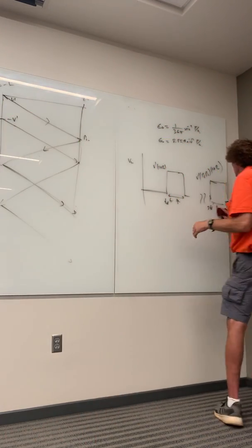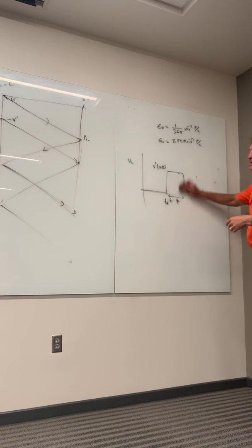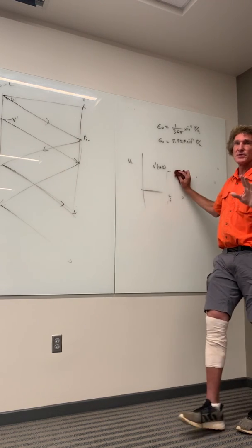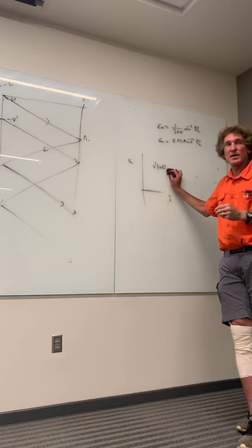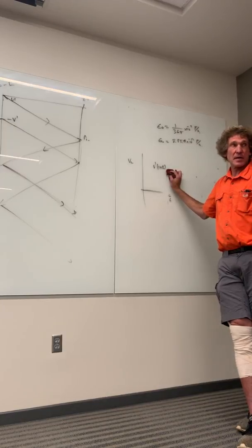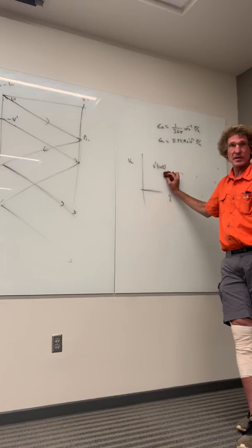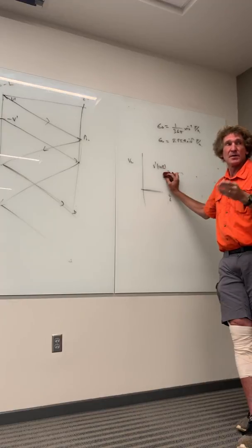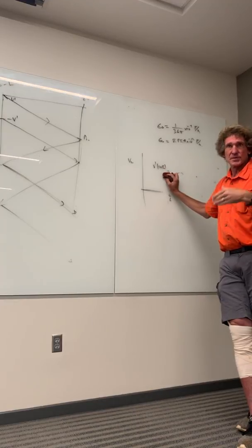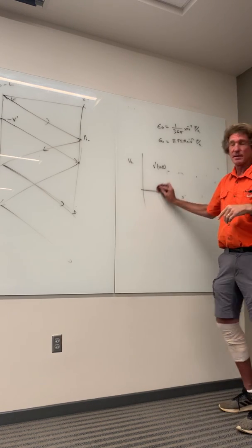By the way, this is kind of an interesting problem, and I'll tell you why. When you talk about digital communications or digital signal processing, anything at short distances, like on chip or on board, they don't FM modulate that. What they just do is send out simple voltages, like 0 to 3.3 volts type voltages down the line, and they are square waves. They usually have a clock, a regular clock that goes from 0 to maybe 5 volts that's transmitted all over the chip. Then they're going to have information in a pulse form like this a lot of times.